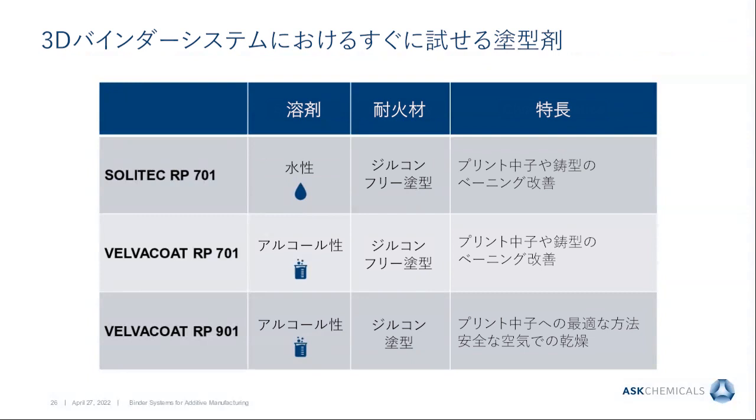Before I get to the concluding remarks, let me put in a few words in regard to special coatings for 3D binder systems. We offer the already mentioned 3 coatings, which are either zircon-free coatings or zircon-based coatings, whereas zircon-free coatings can be obtained in water-based or alcohol-based formulations, and the zircon-based coating is available in an alcohol-based formulation.